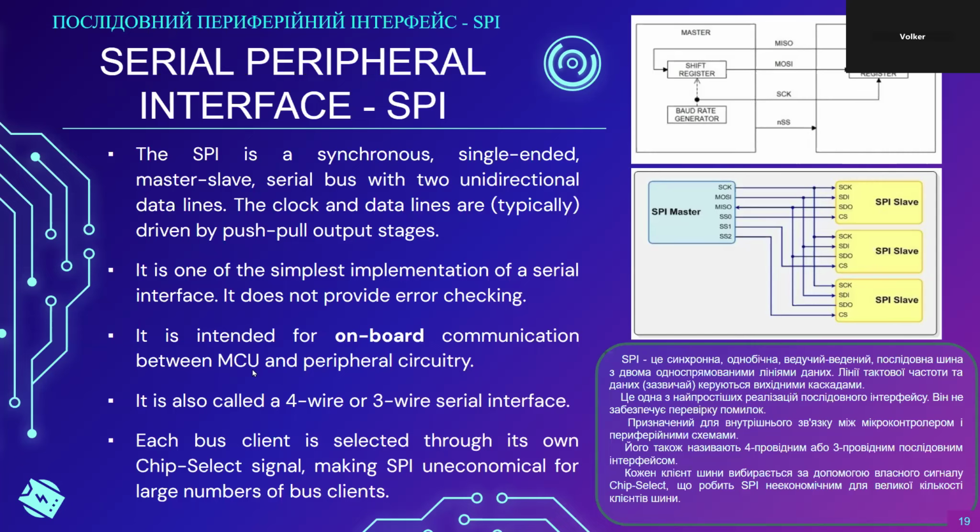If you look at a schematic and you have an unknown serial interface and you don't instantly know what type of serial interface it is, if you see anything that says MISO, that means it's an SPI interface. Some microcontrollers use different names now. But MISO, MOSI, and SCK are the traditional names for these signals.